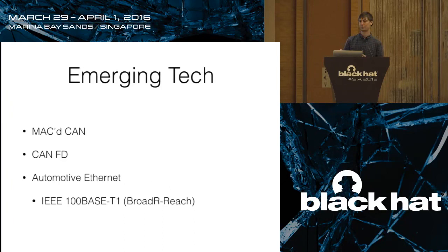You can actually verify that this was from a real controller in the vehicle. Problems with this, well, a 1 byte counter for a message that's being sent at a rate of, let's say, 1 millisecond, you're going to exhaust that counter pretty fast, and if someone's logging these messages, they're going to be able to essentially do a replay attack as long as they can get the counter value and the payload value for a particular MAC. So it's arguable how useful that is to prevent against certain types of attacks.